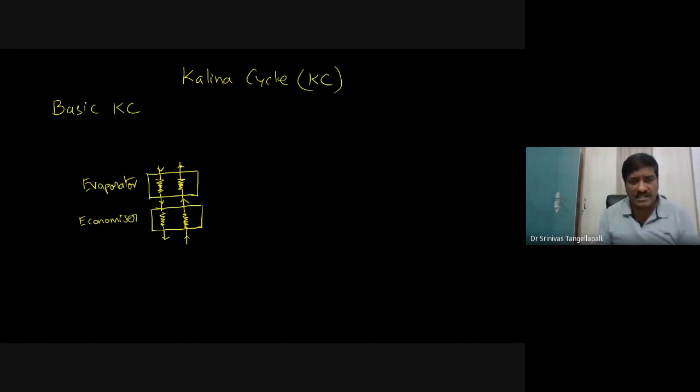But in this Kalina cycle model, before reaching the dew point temperature, the evaporation process is incomplete. If the evaporation process is incomplete, what can we expect? We can't expect 100% vapor. This is not saturated vapor. This is unsaturated vapor, so it consists of liquid and vapor.